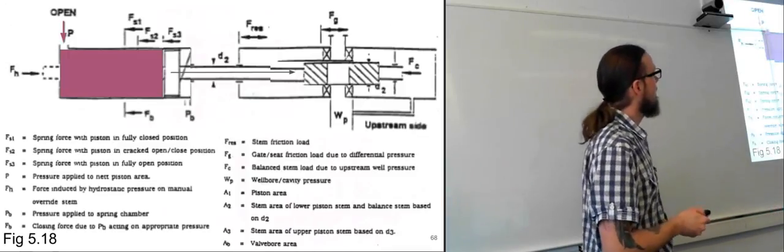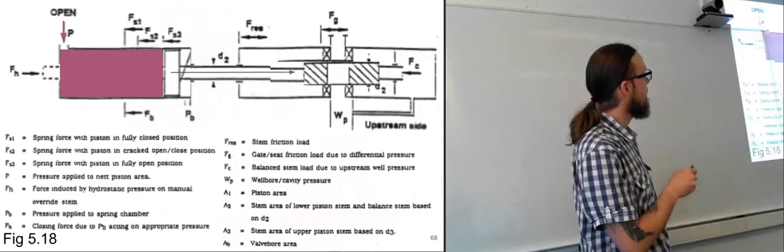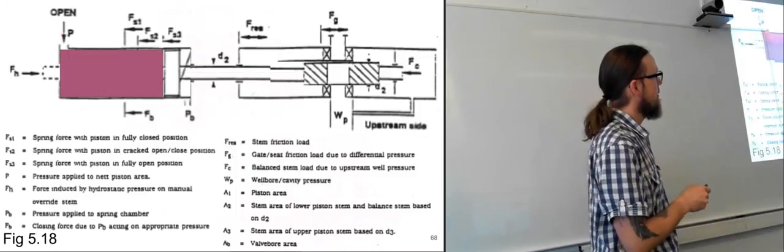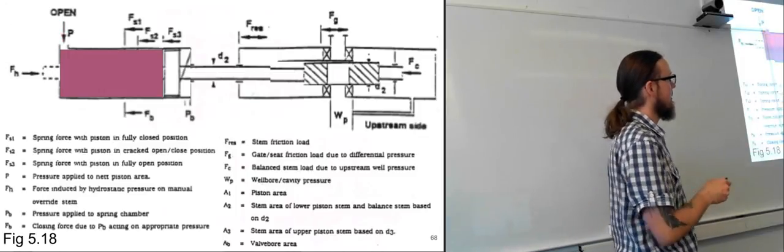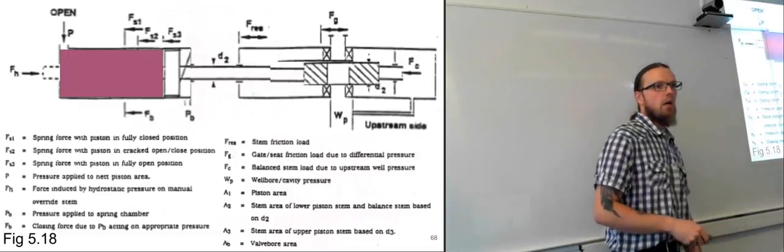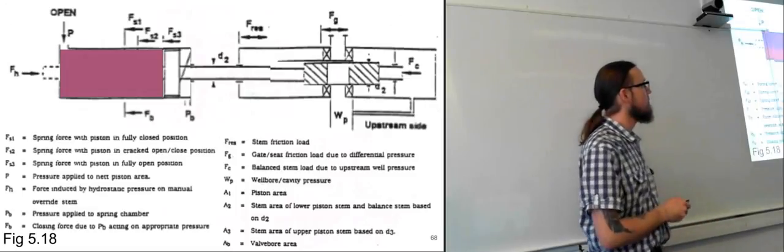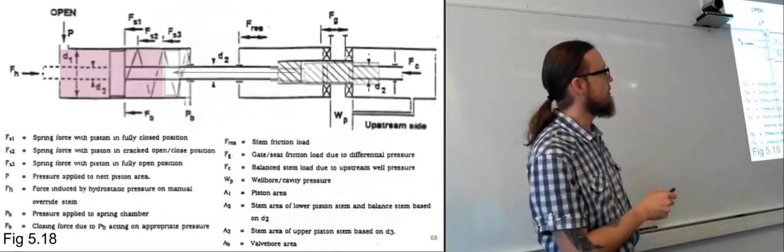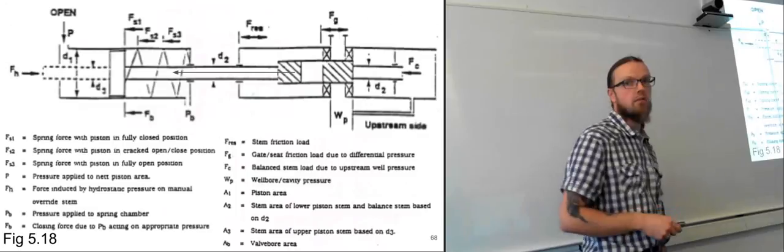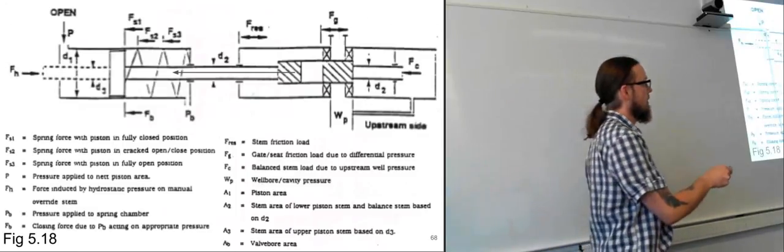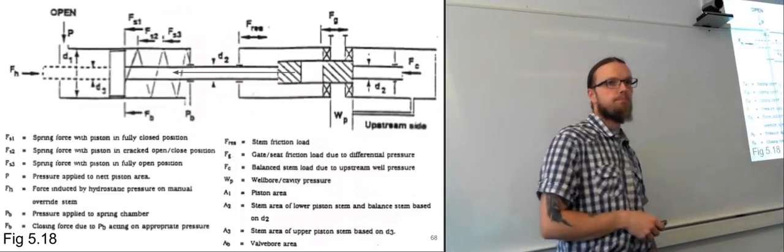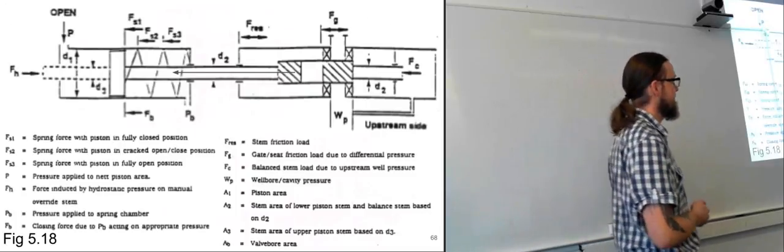And then we stop adding new pressure in here. We just maintain the pressure inside here, and it will stay open. And then when something unexpected happens to the hydraulic force, we lose the pressure and it will snap all the way back on the spring, so that it will close off the production flow, which is what we wanted to do.